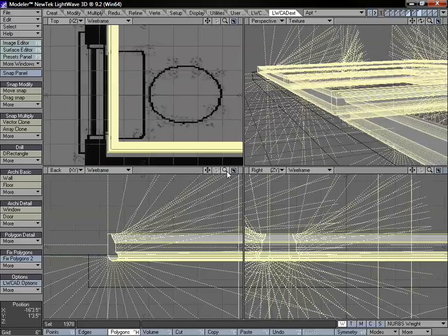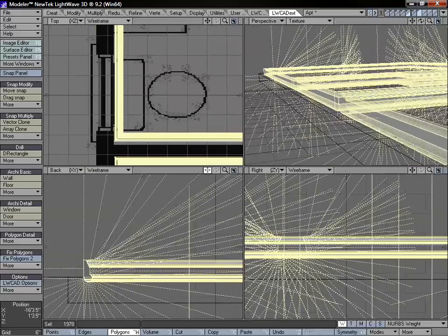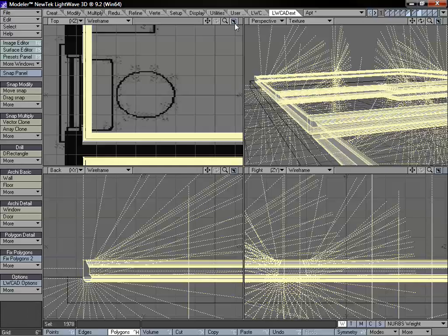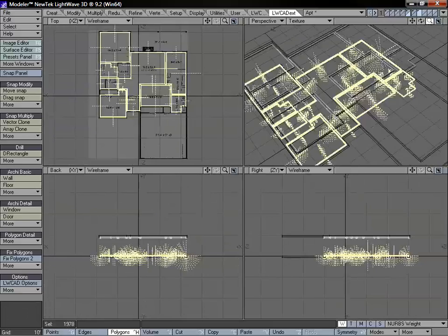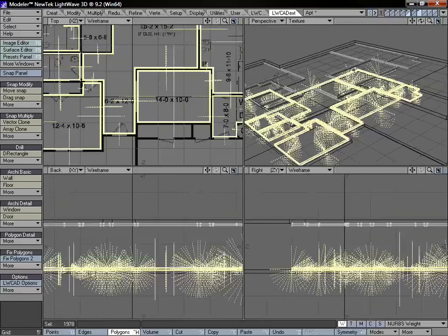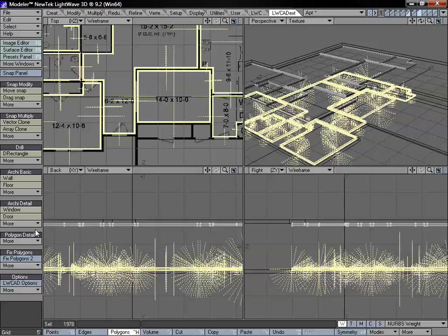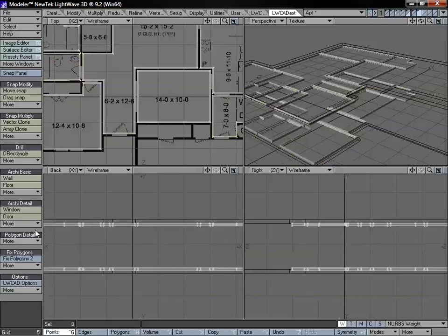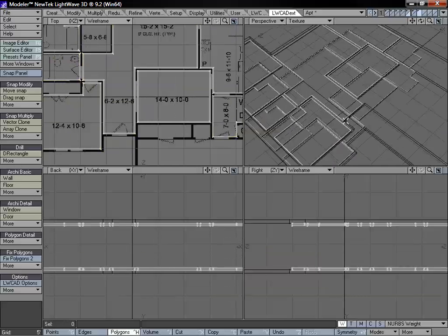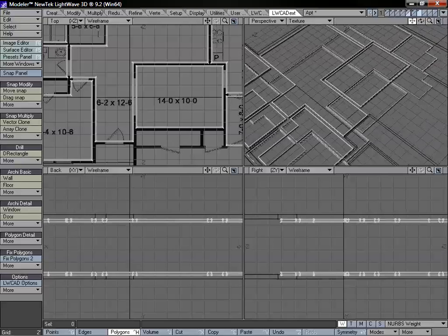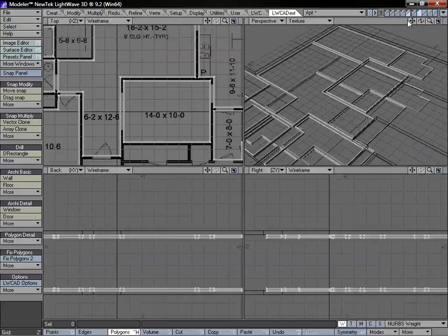If you need to, you can just go ahead along the bottom and actually create a custom trim for that bottom if there's something else you maybe wanted to have different about it. And if you did do it customly too, then you wouldn't have to go along and cut out all of your door regions because you just wouldn't include those lines because the profiler works with open line curves as well.